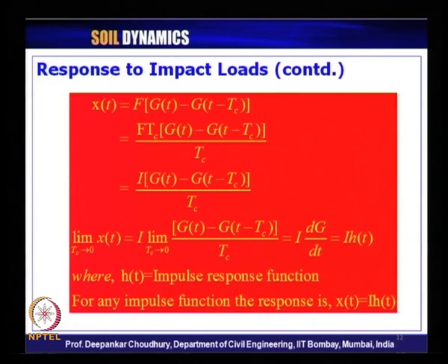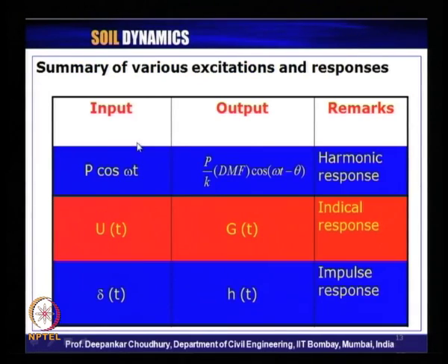So, indicial response g of t for unit load, and the remaining portion we deducted is expressed mathematically as I times dg dt, which equals I times h of t. H of t is called the impulse response function, which is the first derivative with respect to time of the indicial response function. So, this was our summary of whatever we have studied for different cases of forced vibration.